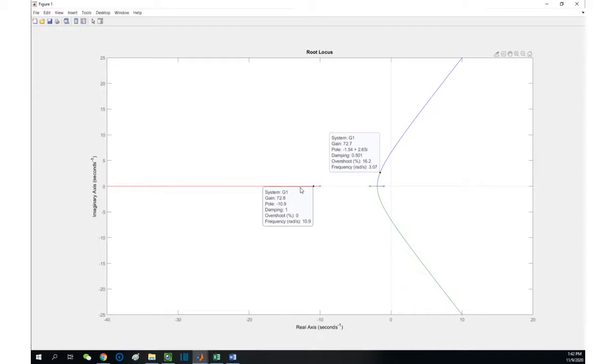Your real pole is not doing anything, actually. It is not affecting or dominating the performance of the system. It's a single real pole, therefore the damping ratio is 1. However, if you have two different real poles, that's actually overdamping.